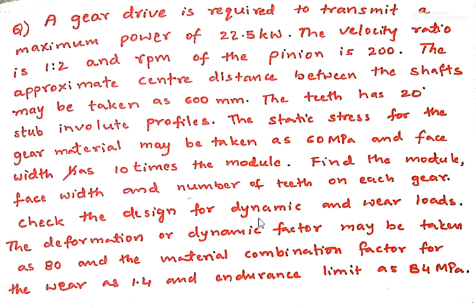Check the design for the dynamic and wear loads. The deformation or dynamic factor may be taken as 80 and the material combination factor for the wear is taken as 1.4 and the endurance limit is taken as 84 megapascal.